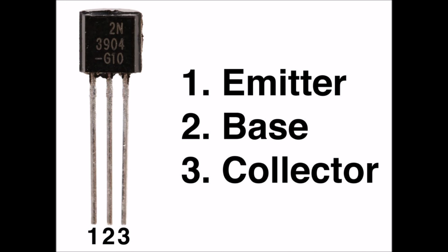Common base circuit. The current gain of a common base amplifier is always less than 1. The voltage gain is a function of input and output resistances, and also the internal resistance of the emitter base junction, which is subject to change with variations in DC bias voltage. Break into oscillation. Amplifiers without compensation are not stable below some specified minimum gain and can easily break into oscillation as shown.